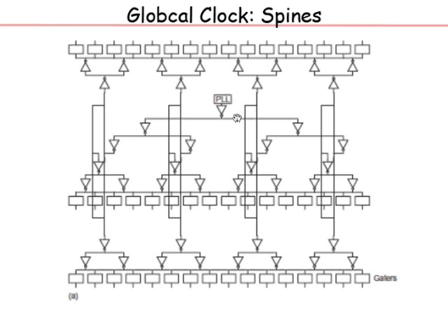Here is another approach. What is done here is what are called spines. This was used in another processor, where from here you have a balanced tree which comes here. It's not like an H, but there is balance, and then from here again it splits into two, and then from here it splits again. From here it goes to the top spine, bottom spine, and then the center spine, and so on. And then finally it comes here.